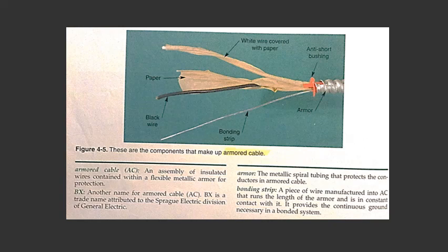Armored cable is expressly forbidden for use in commercial garages, hoistways, elevators or cranes, theaters or motion picture studios. AC is quite flexible and can be pulled through bored holes with ease. The holes should be slightly larger than the cable to avoid strain during installation.